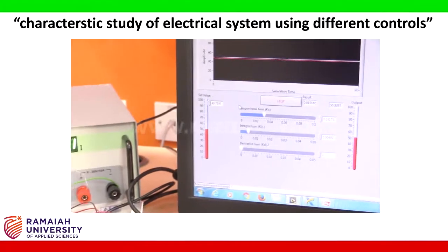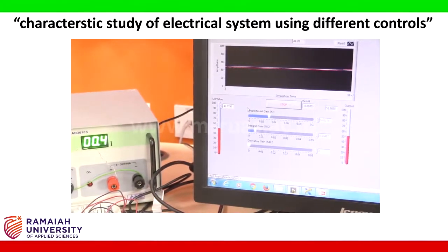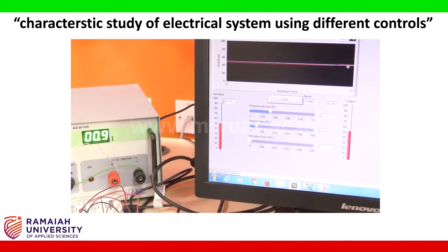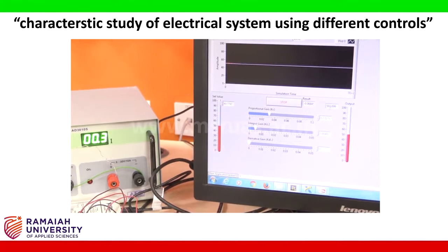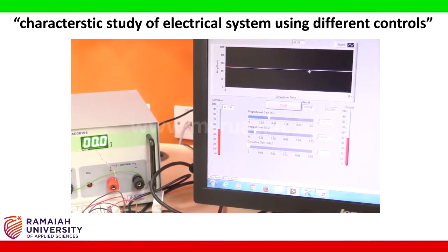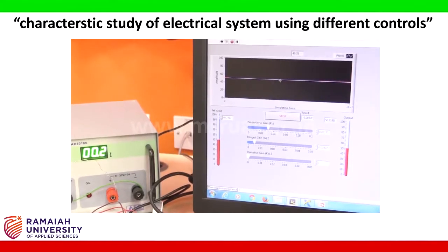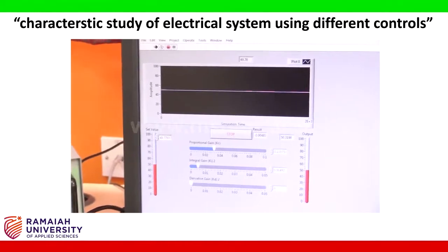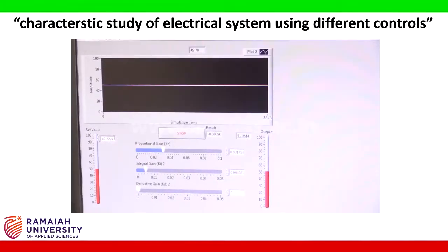Now if you observe, because of the increase in integral gain as well as proportional gain, there is a small overshoot, 49.77, 50. And even though there is an overshoot, because of these parameters, it maintains the temperature on a transistor at the required value within plus or minus 2% of error.